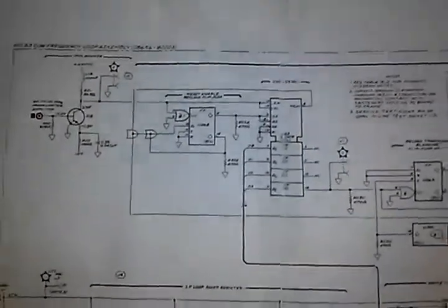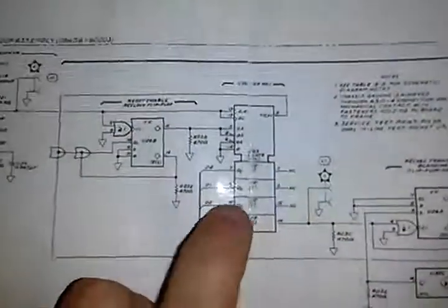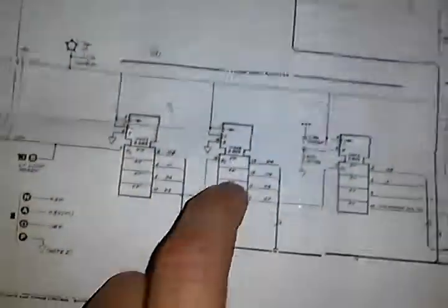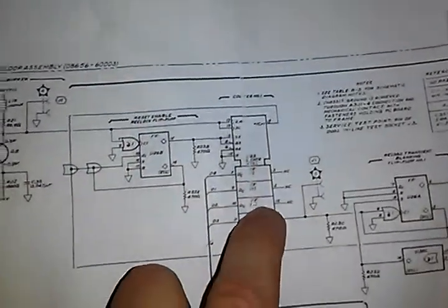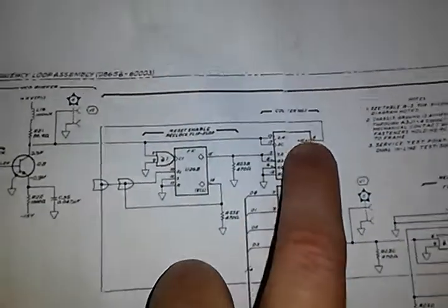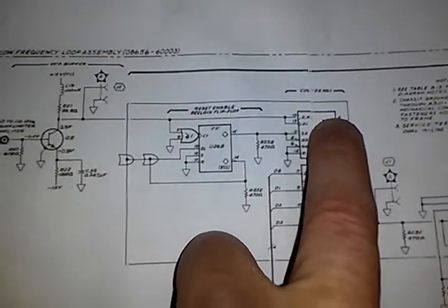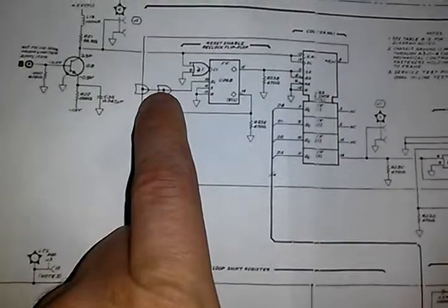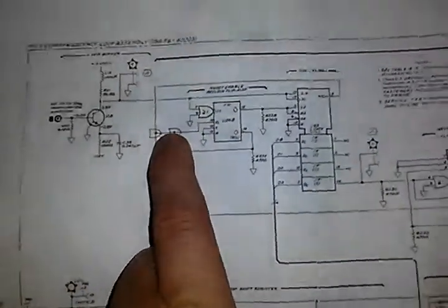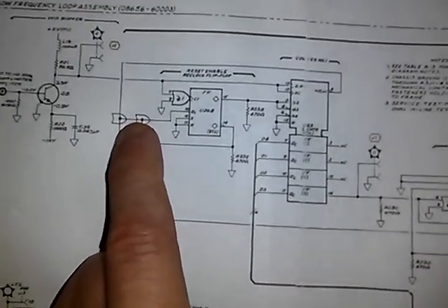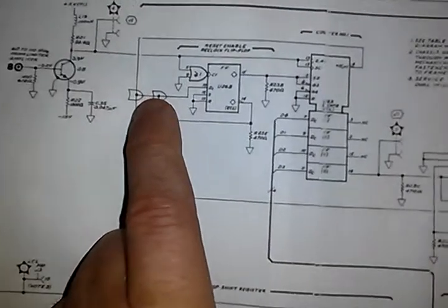So just to diverge a second, I'm going to explain how this works, and I don't have the spec sheet out for them, but I'm just going to explain this very quickly. These inputs are 4 bits, which are taken from these latches, or one of these latches. And when this thing counts to F, that's considered a terminal count. This is active low. This will go low when that occurs. It then goes through this OR gate here, which is a synthetic OR gate. It's basically formed not by a regular gate, but by traces which are connected together.